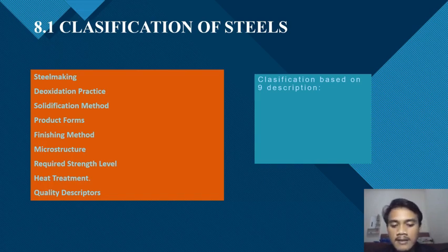Another category of steel based on strength is a group called ultra-high strength steel. These are commercial structural steels capable of a minimum yield strength of 1380 MPa, or 200 KSI, and the types of ultra-high strength steel are medium carbon low alloy steel, medium alloy air hardening steel, and the less common high alloy hardenable steel.